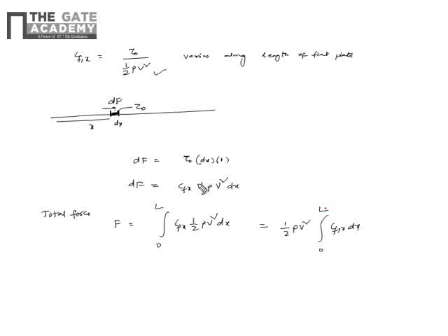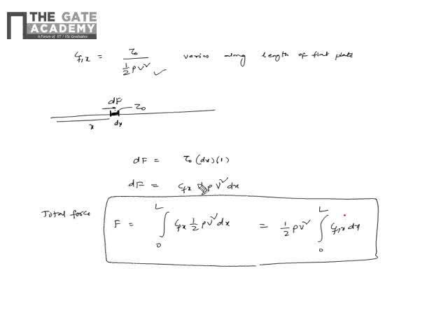So this is the general way of calculating the drag force if the local friction coefficient and how it varies with x is given. Now this variation will depend on whether it's laminar or turbulent. We'll see that later. Most of the time it is also expressed in the average sense.